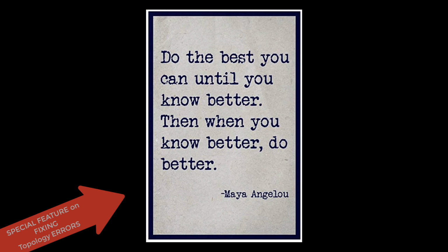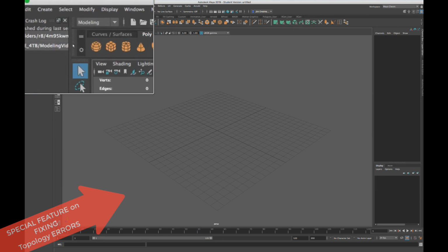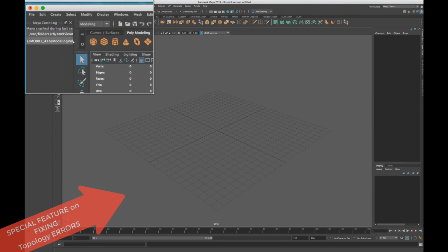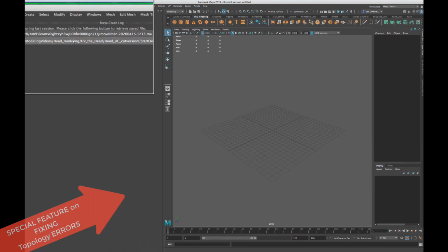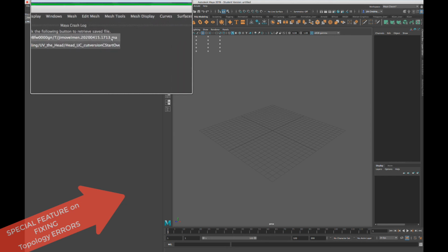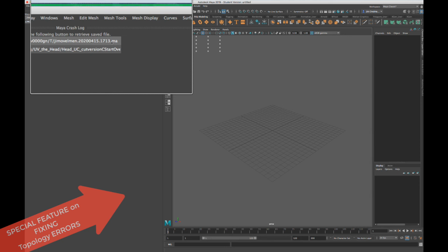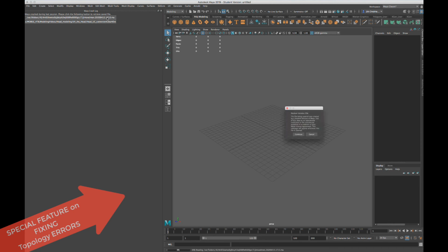Well, one thing that's sort of a reprieve when Maya crashes is when it reopens, it tries to autosave and save a .ma file. You'll see here in the corner a crash log column. If you zoom in, you can see that it auto-loaded a crash save file. That may or may not work. You can click on it. I think most of the time it would have saved it, and if you click right there where the latest MA, it's saved in a default location, it will reopen the last place you were with the file. It's not 100% reliable, as I mentioned, and it might not be the very minute it crashed. It might lose some stuff still, but it is a nice saving grace that it loads it there.